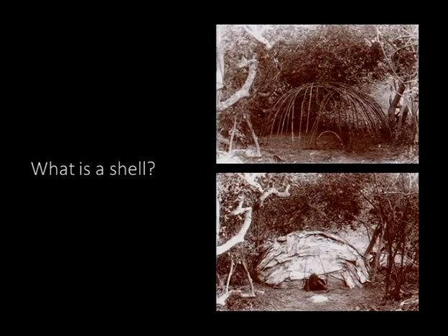The only way to resist bending, I found this by chance, you probably know that, it's definitely a good example. In this case, the thickness is very reduced, so it's easy for me to bend this without breaking it. But if I flip it vertically, in this case, I feel it's much more resistant because this thickness resists to bending. But if I'm able to put this into the shape of an arch, then all the forces are transferred along that surface. So it's like saying that the thickness becomes this one. So you can go thin. All right? So that's the overall principle.